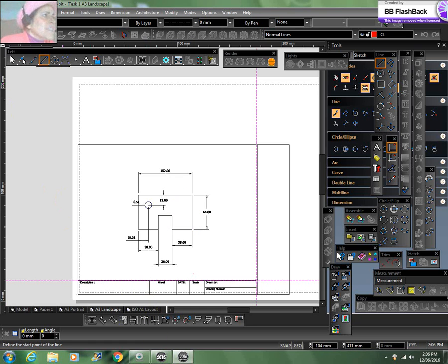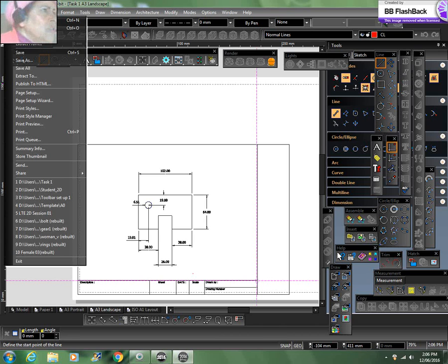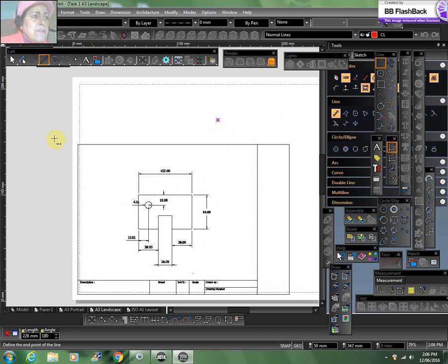And then to print it, you press File and you press Print. Just normally you print, and when you bring this one here, you have a viewport. This image is called a viewport, and this viewport needs a scale. You have to scale it, and in the printing option, you choose the scale of 1 to 2 because it fits into A4 paper.